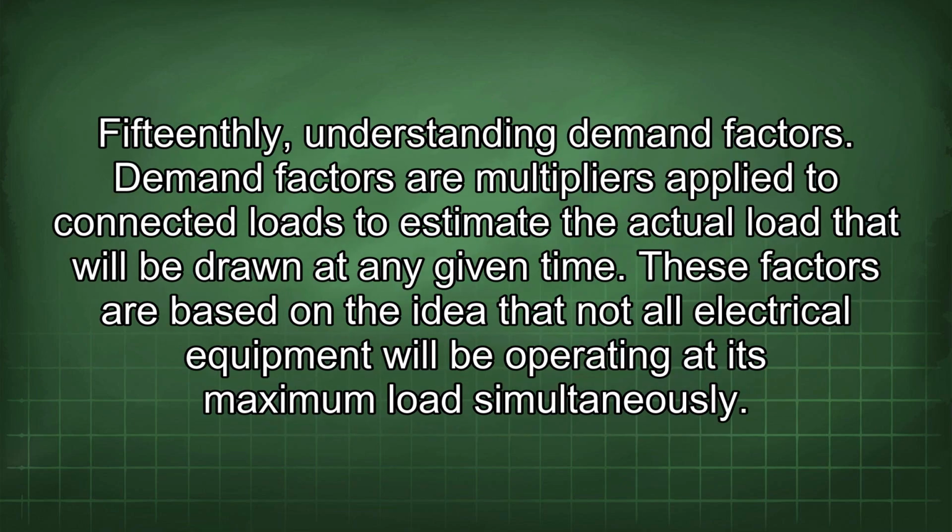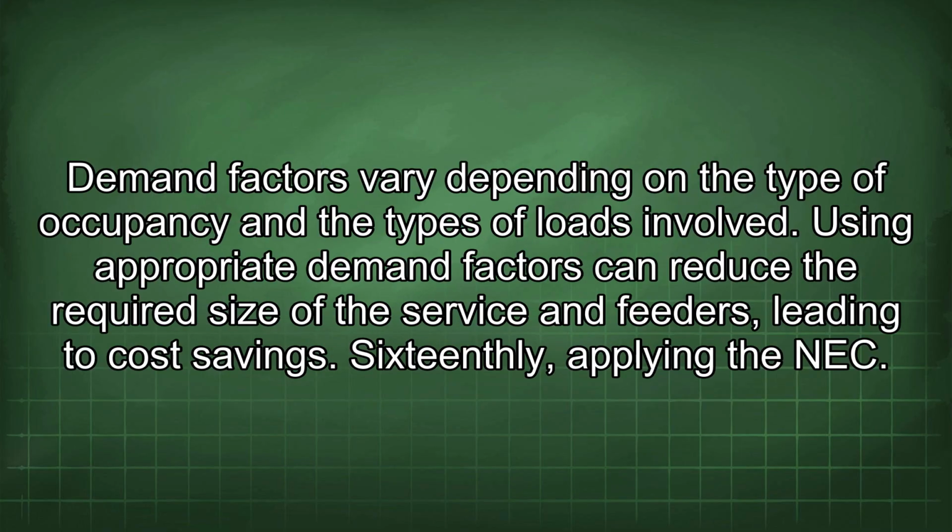15th, understanding demand factors. Demand factors are multipliers applied to connected loads to estimate the actual load that will be drawn at any given time. These factors are based on the idea that not all electrical equipment will be operating at its maximum load simultaneously. Demand factors vary depending on the type of occupancy and the types of loads involved. Using appropriate demand factors can reduce the required size of the service and feeders, leading to cost savings.